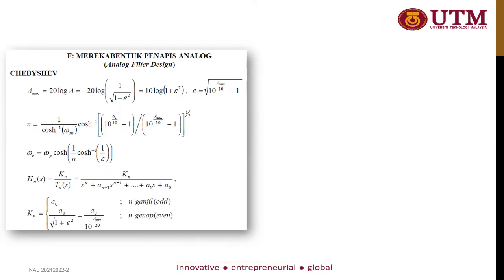Okay, the most important part in this chapter, you need to refer to lots of appendices, and it depends on the type of filter you'll be designing. For example, if you notice that the filter response has a ripple in the passband area, you know it belongs to Chebyshev, so you need to refer to all equations from Chebyshev.